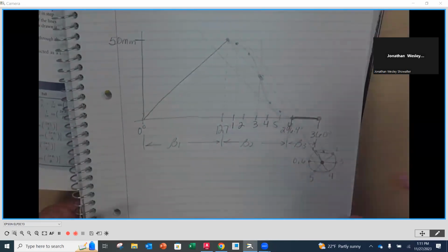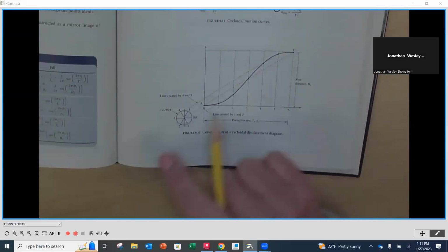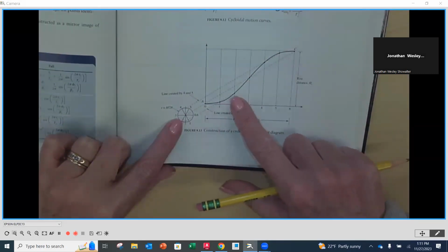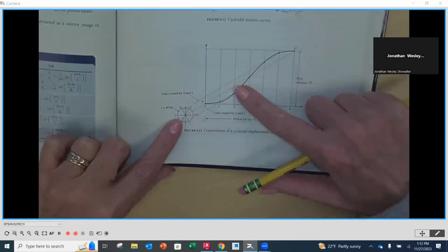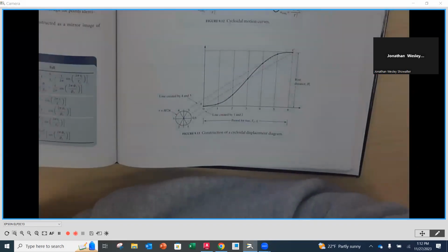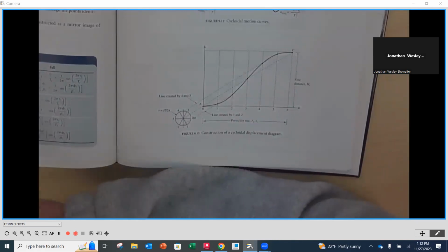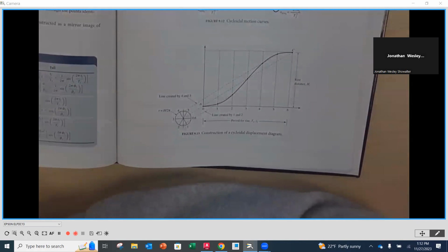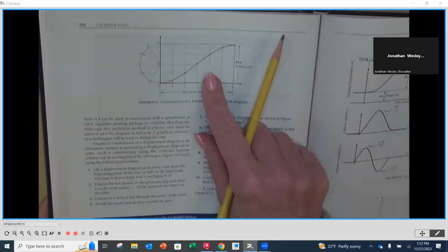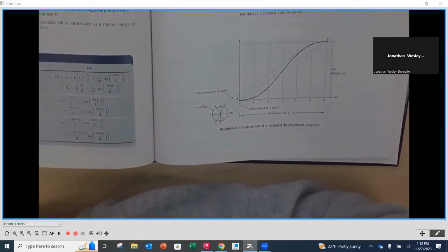Okay, but straight lines, much better constructed along here, as you can see. So everything comes from the centers, and then they intersect with their corresponding section going up. And then the total rise, or fall, is whatever is prescribed for that step. Does that make sense for everybody? You'll maybe get into it and have a couple questions, but honestly, by following each one of these, you're going to be doing a harmonic and a cycloidal for the problems that you have. I think you'll make sense of it. If not, then that's what I'm here for.